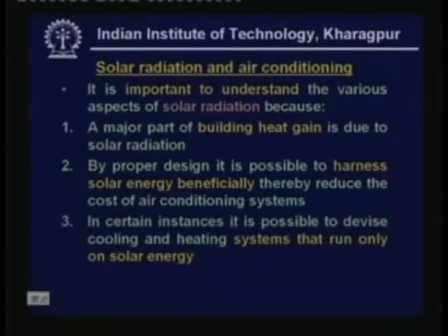And the third reason is that in certain instances it is possible to devise cooling and heating systems that run only on solar energy. This is very important as far as energy conservation is concerned, because it is possible in some cases, for example using an absorption refrigeration system, to devise an air conditioning system which runs only on solar energy.